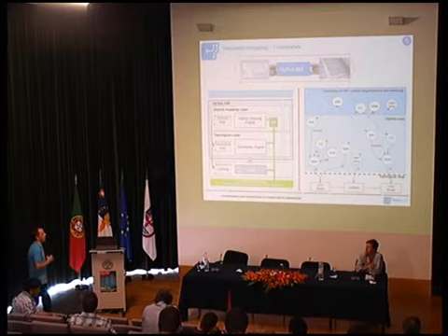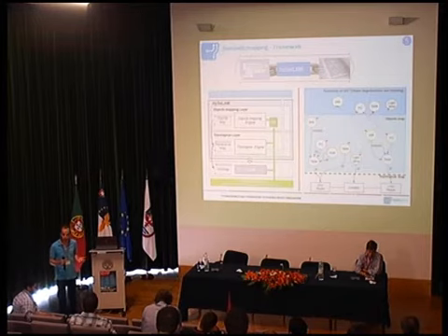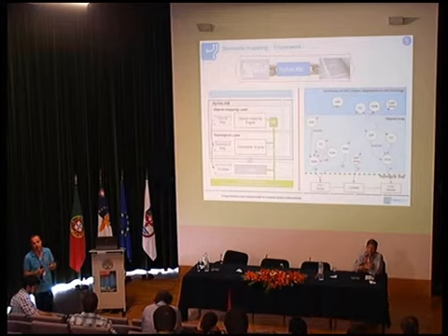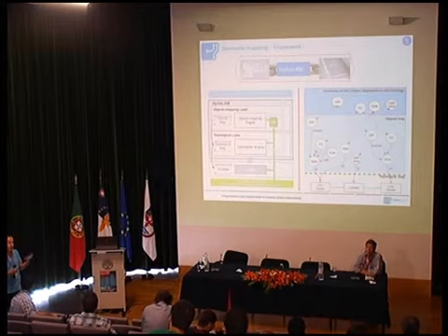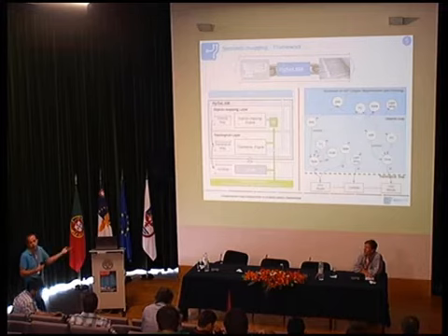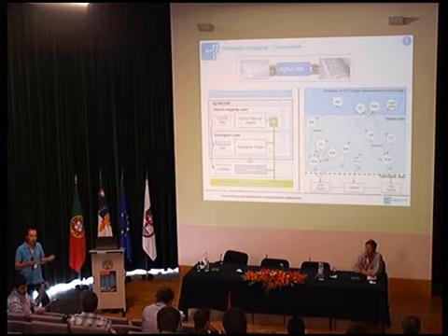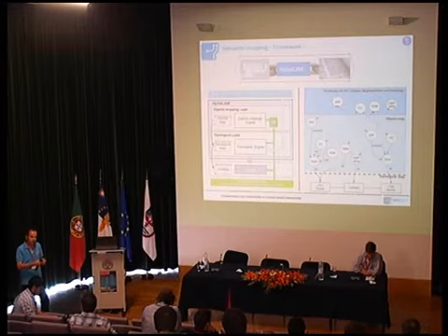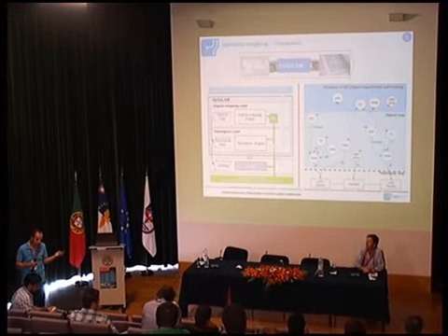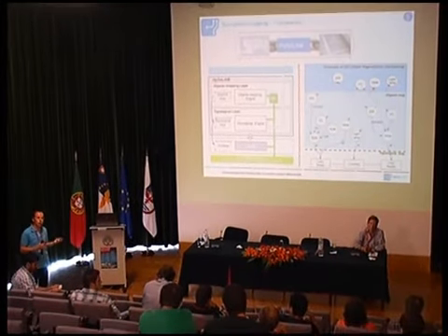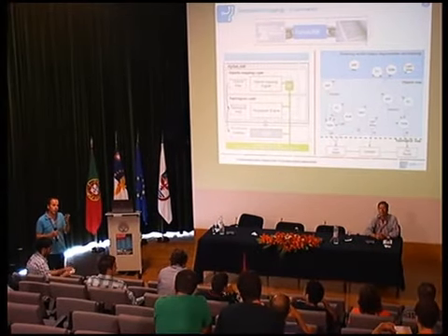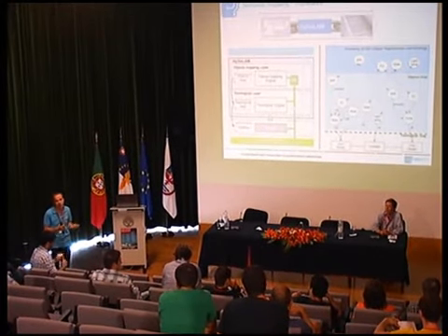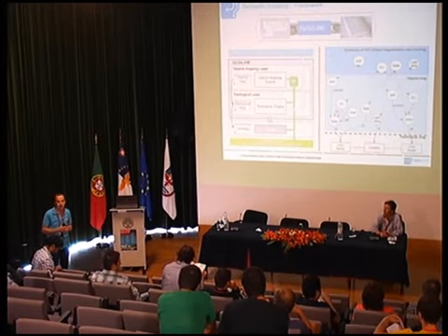They can work in a place that they don't know, because this is iterative. The robot constructs its knowledge. First, it constructs the occupancy grid maps, and then it tries to extract an abstraction of that geometric information and connect that abstraction to human words. This is useful because if the robot does not know how to relate words to objects that are present in the environment, you cannot do what you want.